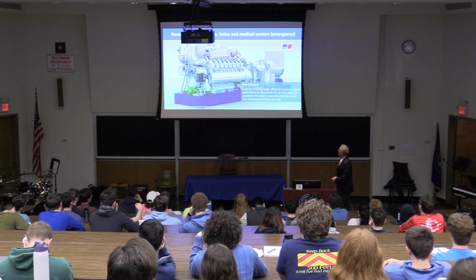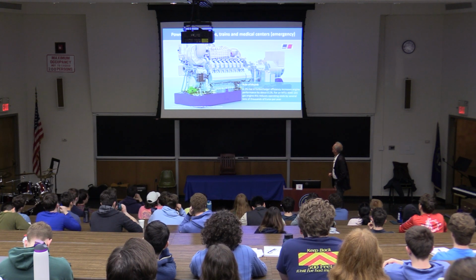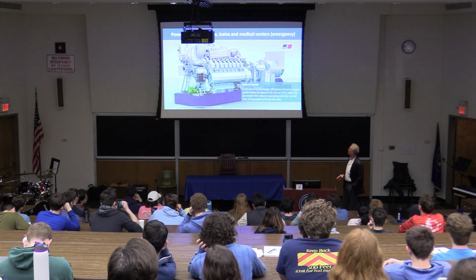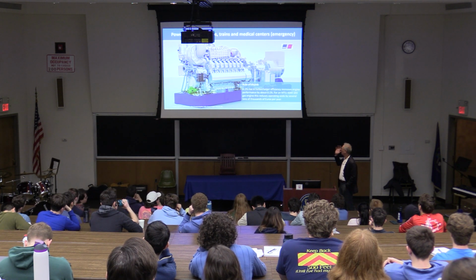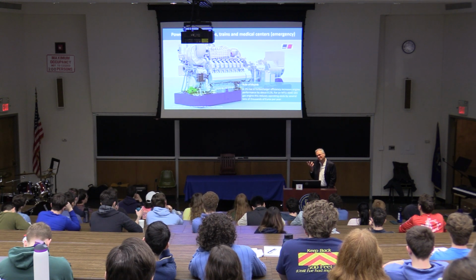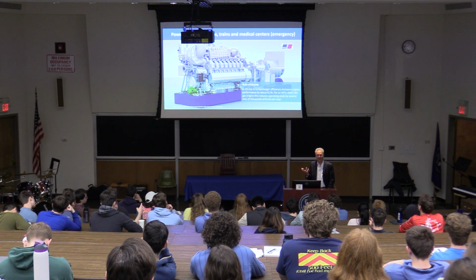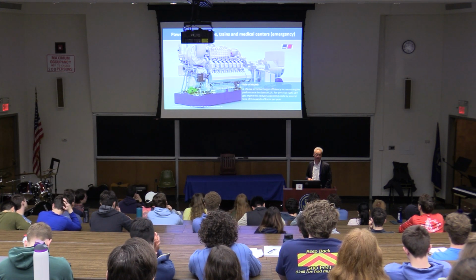But they computed that a 1% rise in turbocharger efficiency increases engine performance by about 0.1%. And that makes up several tens of thousands of dollars or euros per year if you run that engine. So it's smart to invest a little bit of time and effort to really save that, because that engine is probably running for 25 years.